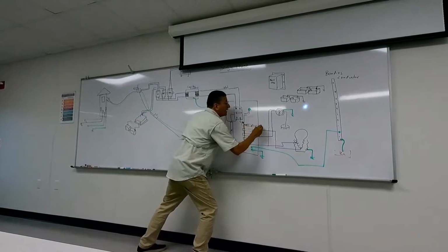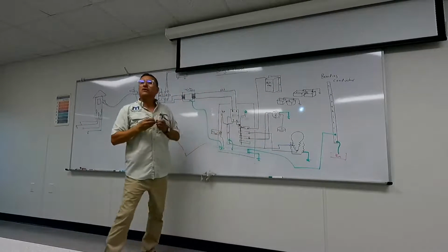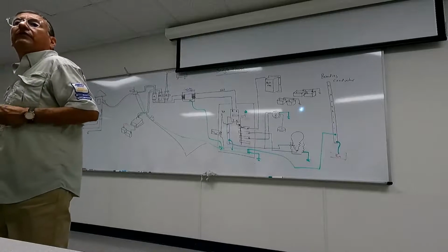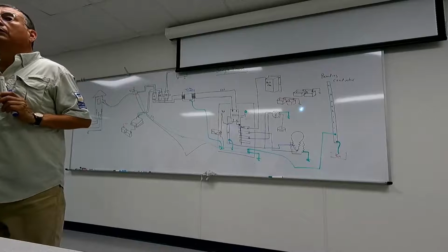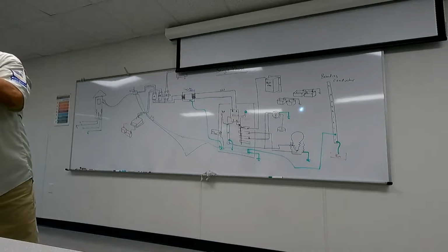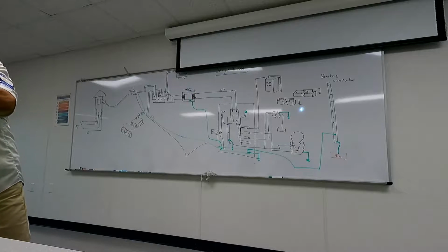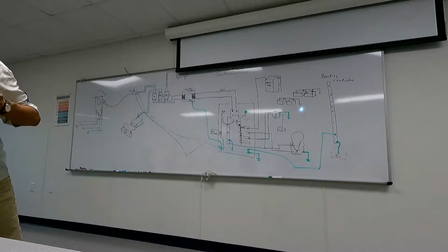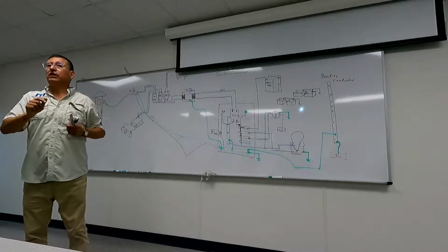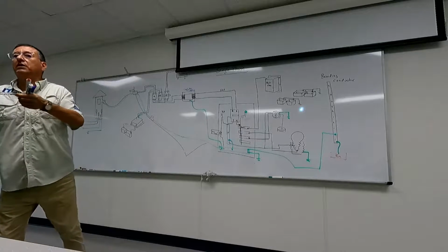Usually the battery chargers come with prongs, no, that you put in the outlet. You plug it over there. So you cut the wires to connect it to your AC panel? Correct. You don't have a plug. You have the cables, hot, neutral, and ground, and they go directly into the panel. And one breaker will be for the battery charger. That's clear? Yes. We are going to cut the plug, split the cables, and connect them in the panel.